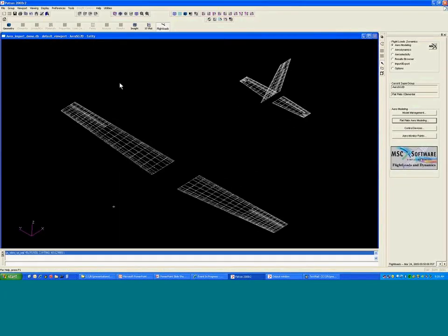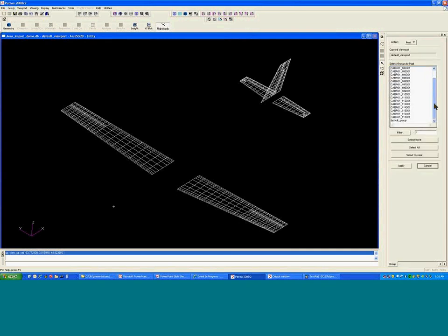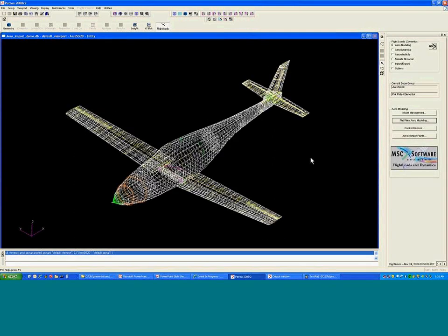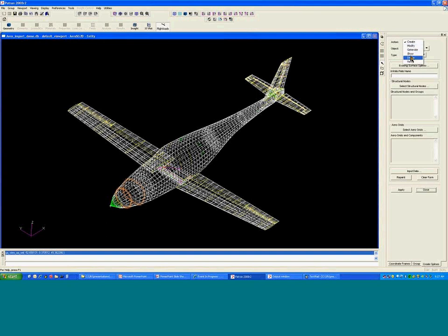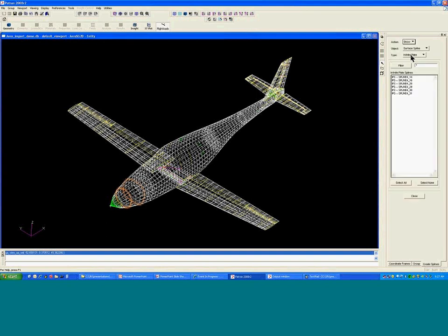So this is our aero mesh, and if I come back to post my structure as well, I've now got the structure and the aero mesh posted. Now, since I inherited this model, another thing that's often of interest is, well, someone gave me this model, and there's a bunch of splines in the model. In fact, I can come in here, go to aerostructure coupling, and say show. When I imported this, let me look at all the different splines in this model.